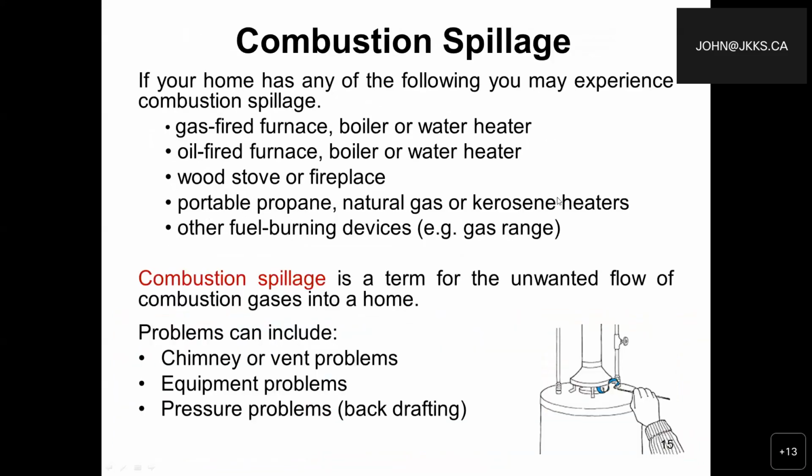Let's talk next a little bit about combustion spillage. What is combustion spillage and why is it important to indoor air quality? Well, combustion spillage gets back to carbon monoxide buildup potentially in a house. So if we take a look at it, when we talk about the building envelope, we need proper and safe discharge of any fuel burning products of combustion.